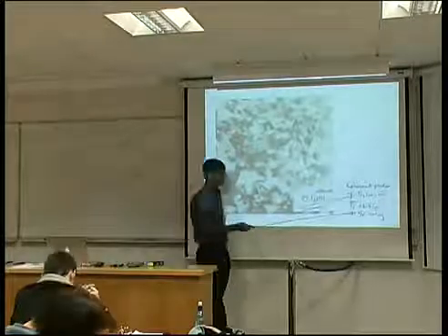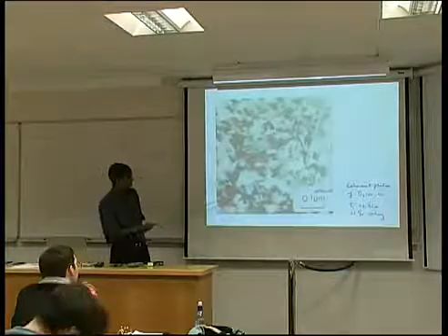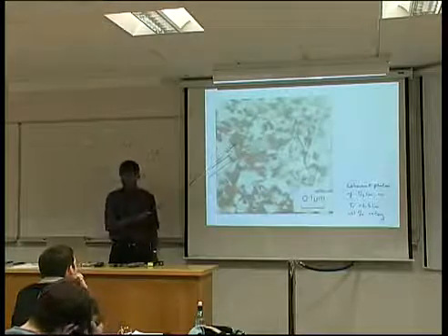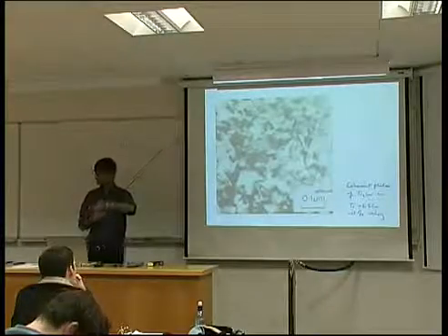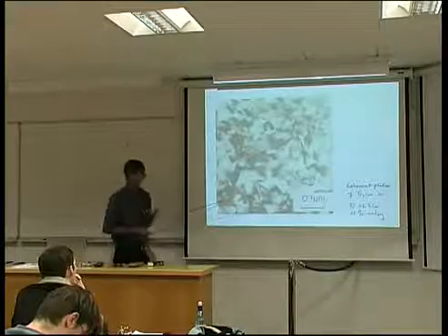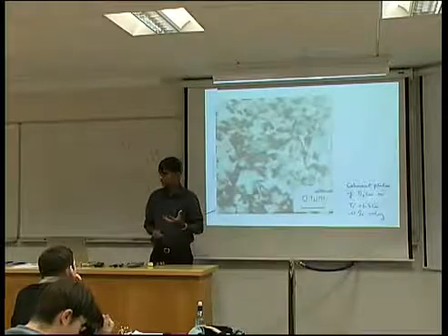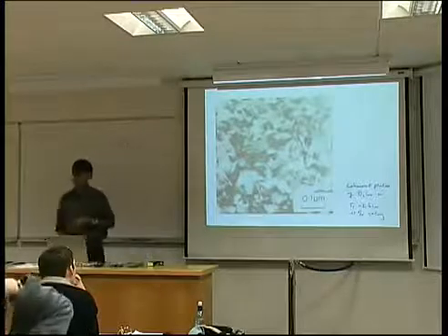So this is a popular alloy in which you precipitate Ti2Cu. You can see the Ti2Cu. And these dark regions that you see are strain fields. Yeah, this is a transmission electron micrograph, and if you have strain, then you'll get diffraction effects. So these coherency strains, they harden the material. So this is a precipitation hardened alloy.